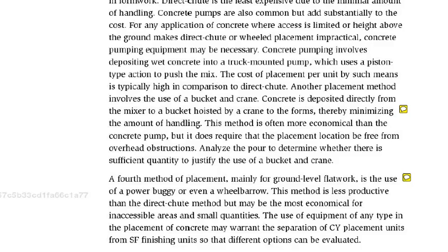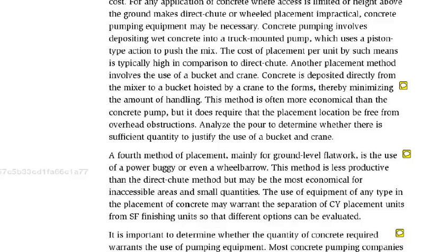You can run the concrete right out of the truck through its chute. You can use a pump, which is expensive. If you need to move the concrete a ways, you might use a mechanized buggy, or if conditions are really tight, you may have to use wheelbarrows. And you can see the more you handle that concrete, the more equipment you need, and probably the more your cost is going to run up. You're going to need to break your concrete work down by how you're going to put the concrete in the forms, in addition to those things we talked about right at the beginning.